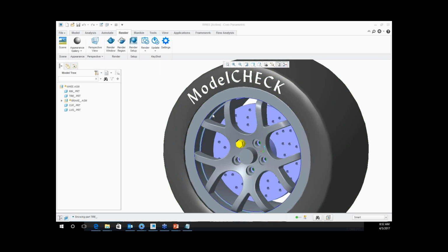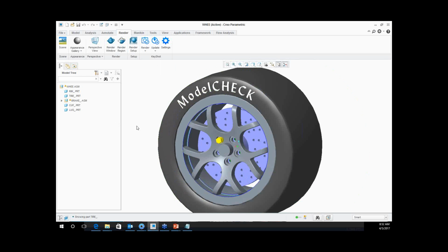In the same way with an STL file, if you're using flat triangles to represent a curved surface, the more triangles you have, the more accurately you're able to capture that curve, compared to fewer triangles. In this case, I have a lot of round or curved surfaces on this model, so I want to make sure that curvature is accurately taken into account when I get it into Keyshot.